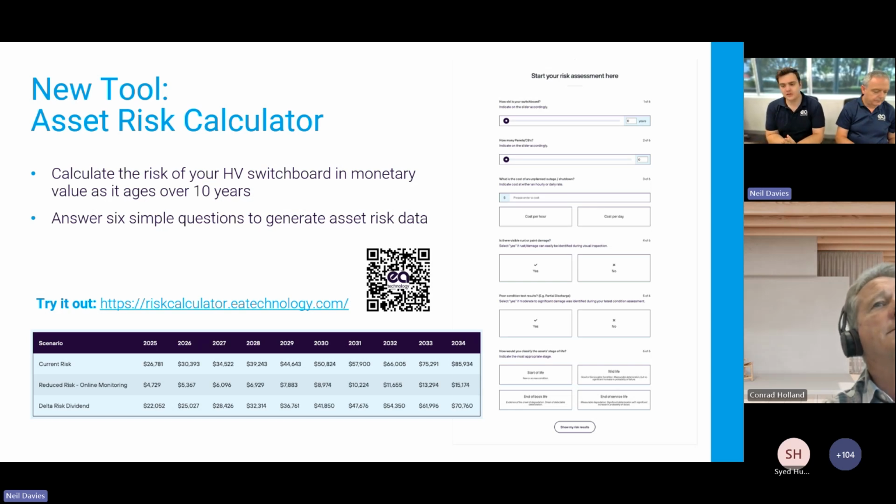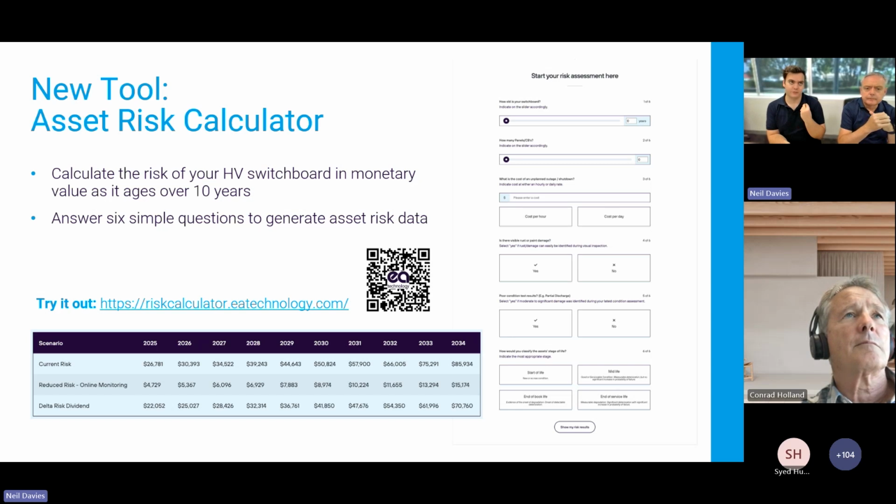So for each asset type, when we start to determine how we're de-risking via monitoring, we basically get the breakdown of what is the likelihood of a defect going into a fixable incipient failure, a moderate failure, or a catastrophic failure, and installing monitoring lowers the number of catastrophic failures, the number of moderate failures, but then ironically in turn you have more incipient failures, which you can get to and fix during scheduled maintenance. So that's how the different risk categories are created for unmonitored and monitored assets.